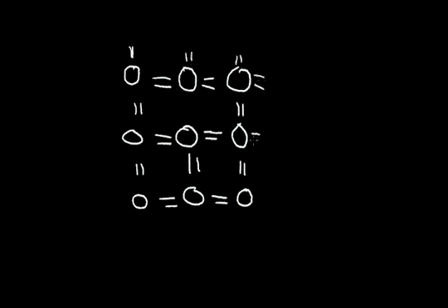So we can draw the nucleus of a silicon atom. Let's draw another atom here, an atom here, an atom here, and so on, etc. Now each silicon atom has 4 outer electrons that can be shared with adjacent atoms. So we have 2 electrons, 2 electrons, 2 electrons, and so on. The structure just repeats, and so on. So we end up with a very stable crystalline structure.